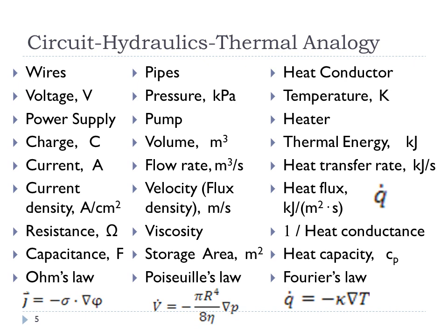So there's a heat transfer rate, which is the amount of energy in the phonons being moved, and you can always normalize that by the cross-sectional area of the heat conductor. So for the glass window case, we're talking about the area of the glass window. If you calculate all the heat flowing through it and then divide by the cross-sectional area, you get the heat flux. And the equivalent to resistance is 1 over the heat conductance, the thermal conductance. And here, the analogy to storage is the heat capacity. So that's that C sub P.